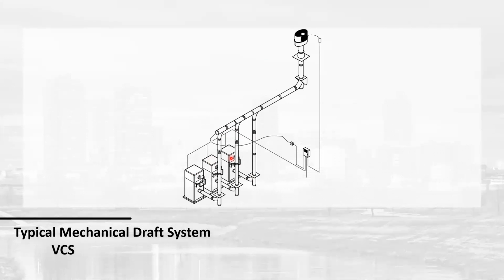Especially in a setting like this, I'm pretty familiar with some of the products that DB Sales has sold on the boiler side. I know one of their manufacturers' control sequence will ramp the boiler up to about 60%, and then turn on a second boiler. So you're not getting 100% CFM versus 100% CFM. It's 60% of CFM versus that 100% during pre-purge. So you'll actually overpower the running boiler. You just have this system that's cycling over and over on a block flue switch, because block flue could be an automatic reset. So you'll have a lot of cycles, but you won't have a lot of run hours. And that's how you can tell that you have a venting issue, if you're constantly short cycling the boiler.